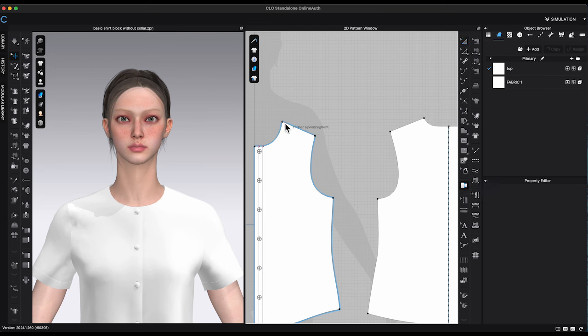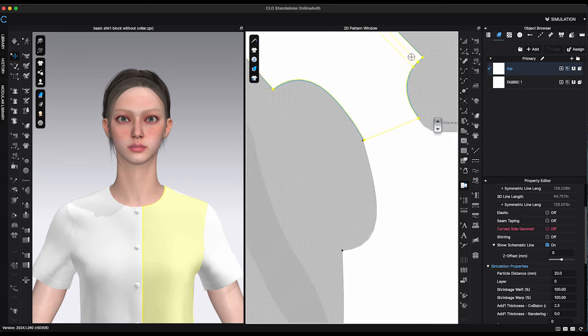Select front shoulder neck point. Then click back shoulder neck point. Slide cursor to match the two shoulder seams. Right-click and choose Move Walked Pattern to intersection. Using this function, you can also check if both seams are the same length.